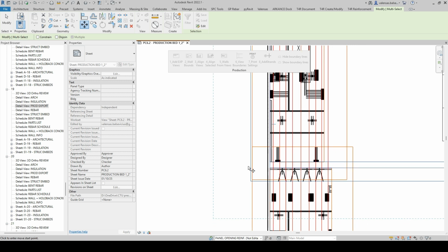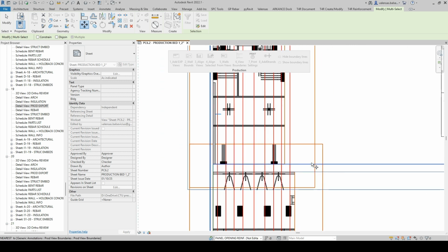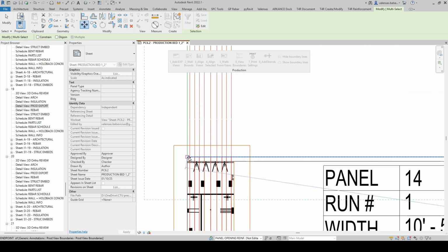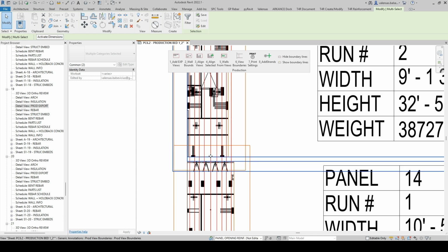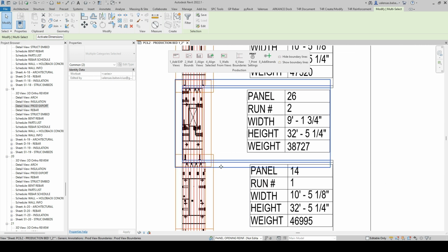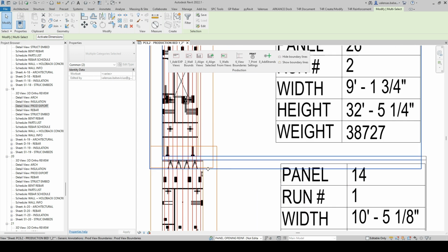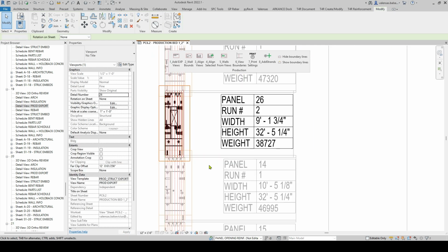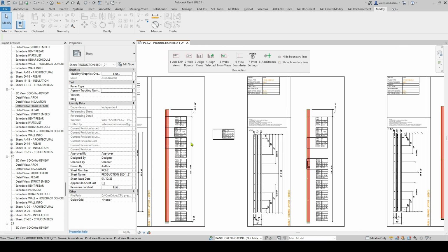You see, I can snap to this generic annotation family, but because it matches the size of the wall, I can just do it like so, and then move it to here, right? And then I still have this 1 foot in model units and half a foot in paper units,